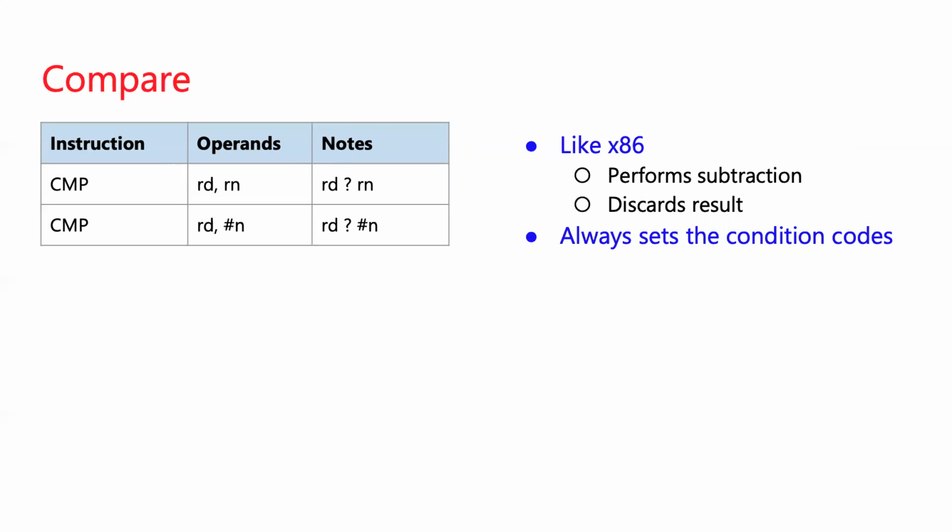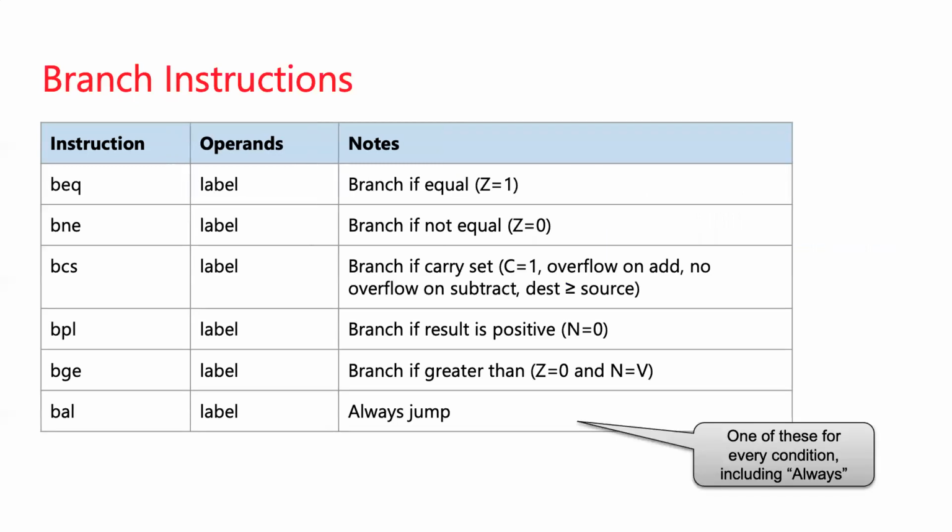Once you've set the condition codes, what can you do? Well, there's a whole pile of conditional branch instructions, and they all start with a B. You can read that as a branch. So this is a conditional jump in the code. And remember when I was talking about the comparisons, I mentioned things like EQ is the name of the equality comparison, or NE for the not equal.